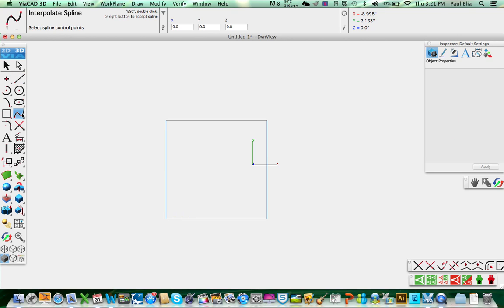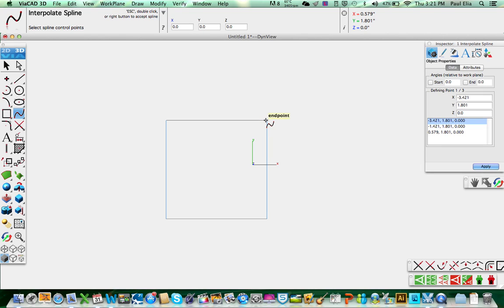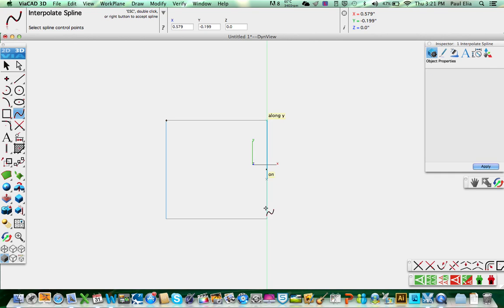Now we're going to go to the spline tool. Remember the spline tool we used in a demonstration? You click, click, double click. So we're going to click. This time click in the midpoint and then double click on the end point. Again, start there again, clicking once. Once again the midpoint, double click at the end point. Click one end point, midpoint once, double click twice.